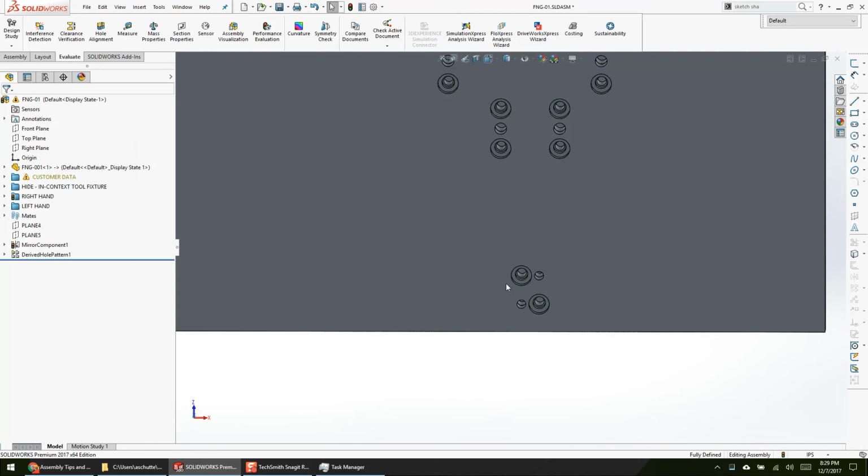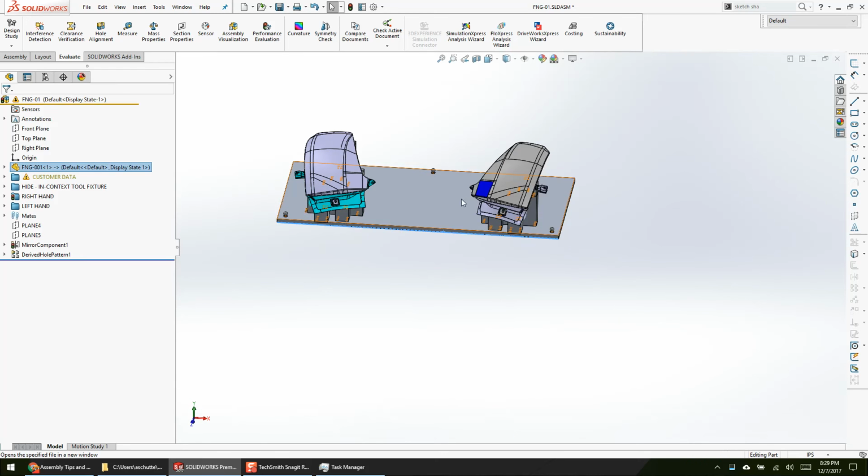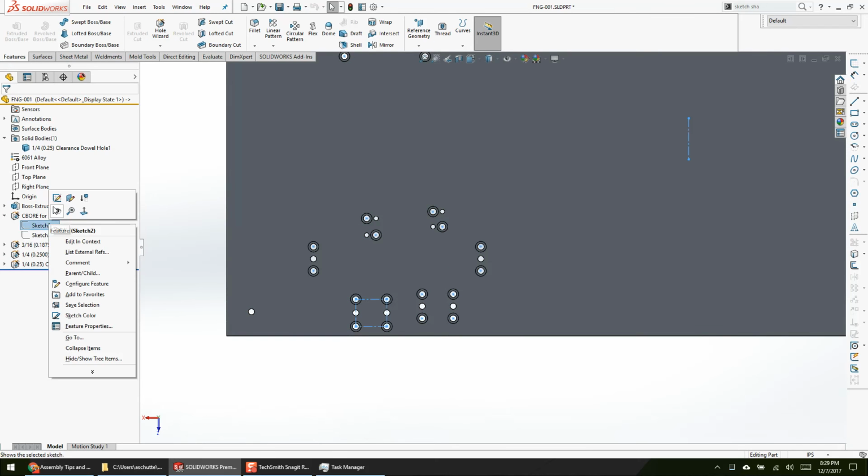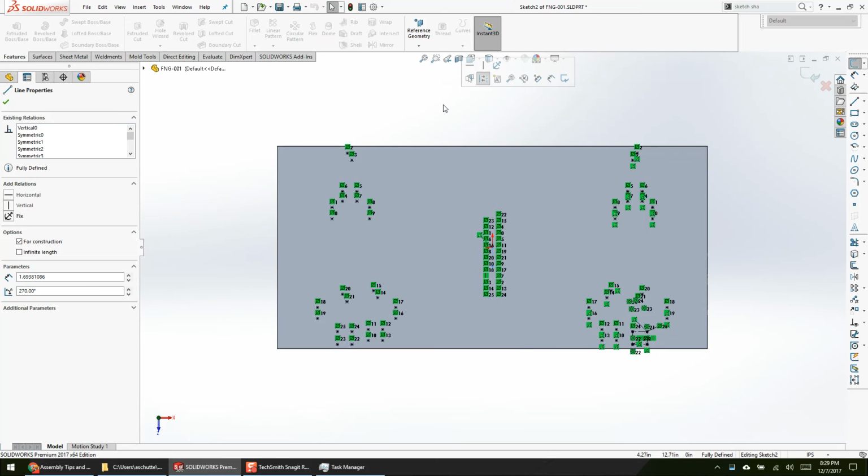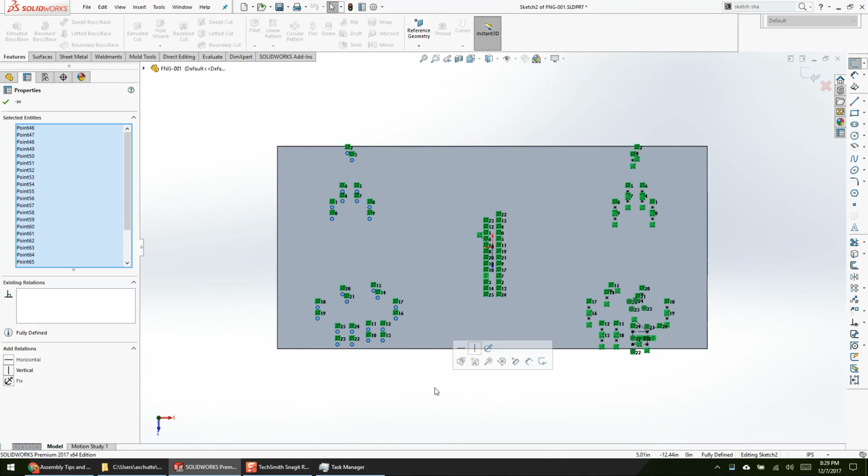And to limit my liability, I only did external references on half of the design, center, origin design, and I mirrored all the holes. Because every single time I say this hole belongs to this part in this assembly, that part could change, that assembly could change, something could blow up, and I may have to fix every one of those holes, legitimately or illegitimately, right? I give the design over to Bob, and Bob blows it up and gives it back to me, and I don't know what happened, I gotta fix it. Or I could have changed something legitimately, or a lot of things could happen, right? But I only ever wanna fix half of my holes.